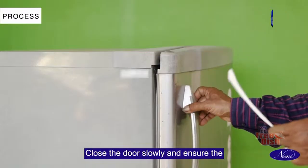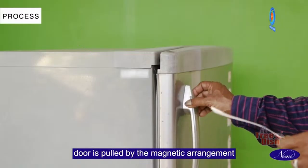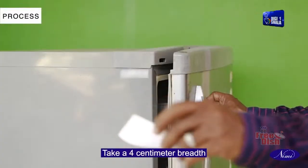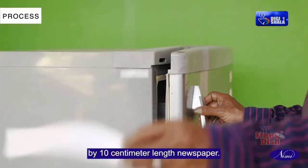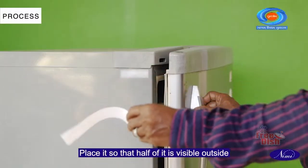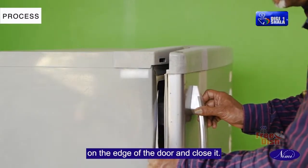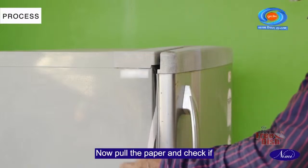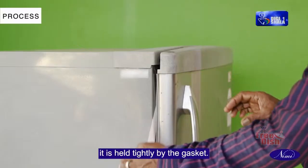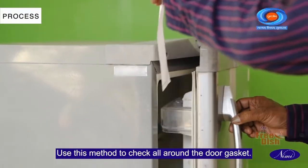Close the door slowly and ensure the door is pulled by the magnetic arrangement when it reaches the nearest closing point. Take a 4 cm breadth by 10 cm length newspaper, place it so that half of it is visible outside on the edge of the door and close it. Now, pull the paper and check if it is held tightly by the gasket. Use this method to check all around the door gasket.